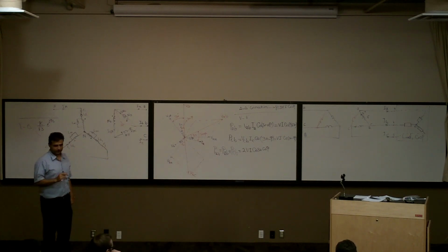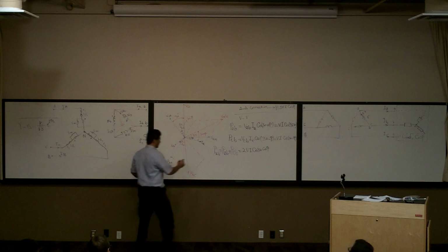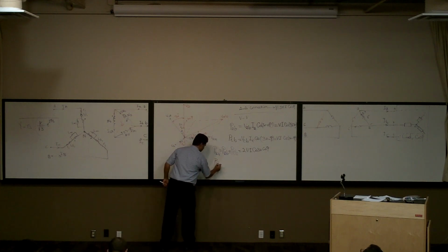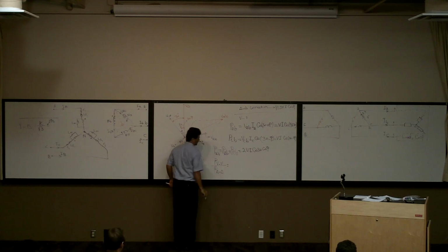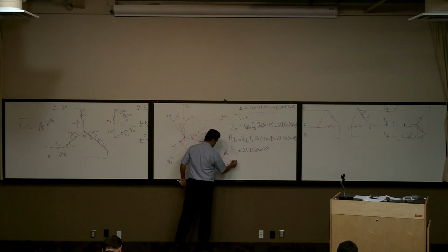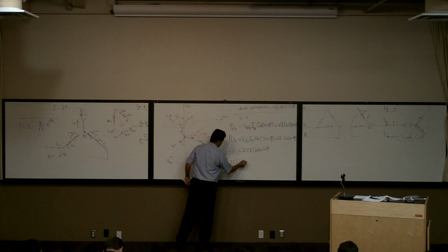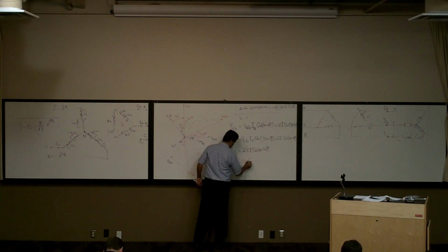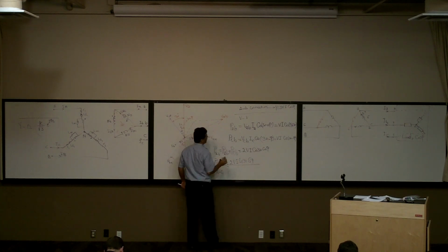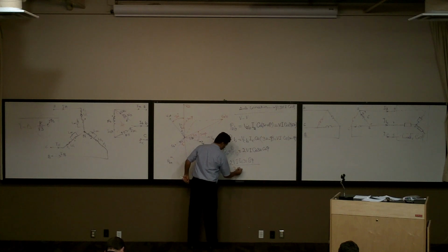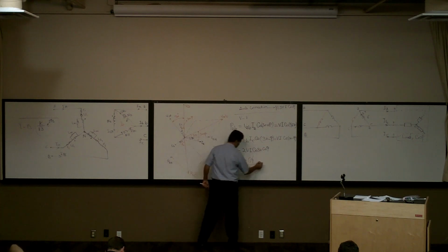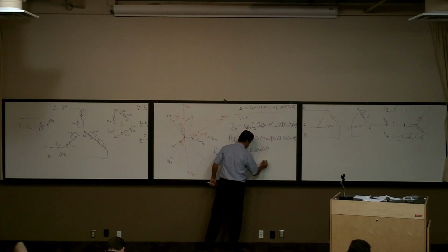Right? Now let's write it here. PVV over P delta. P delta is going to be 3 VI cosine phi, so it's going to be 2 VI cosine 30 cosine phi over 3 VI cosine phi, so it's going to be 2 cosine 30 over 3.